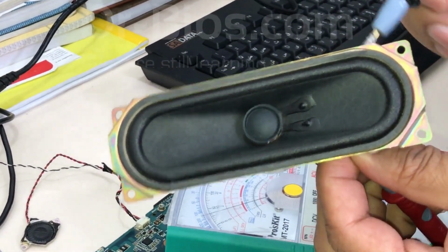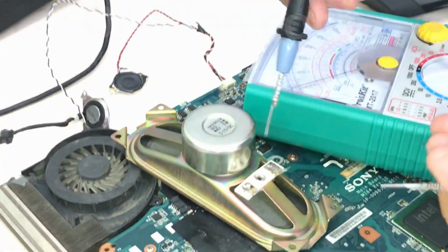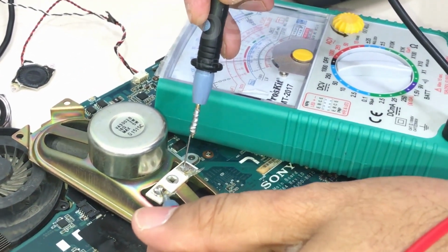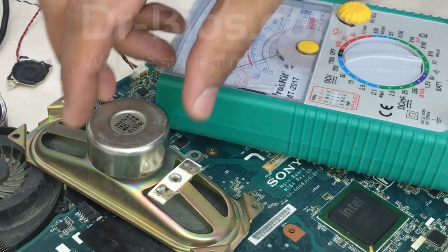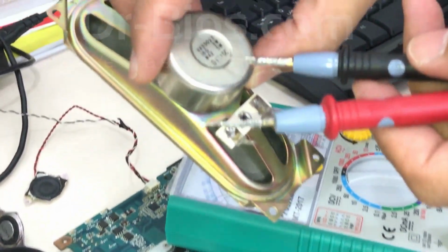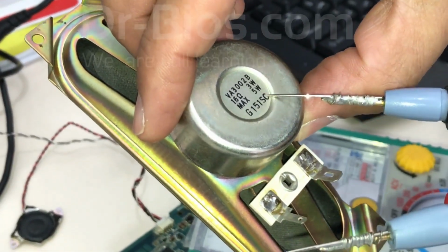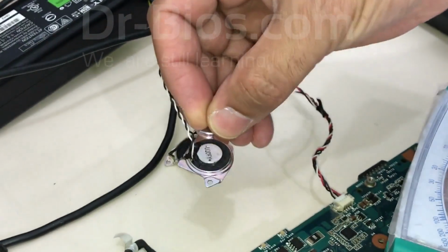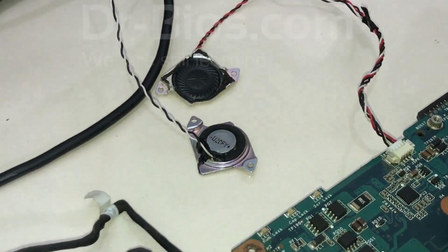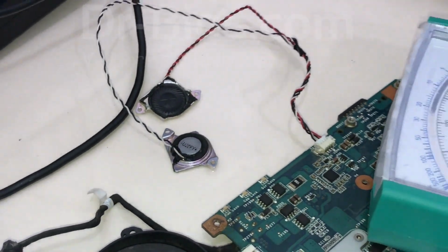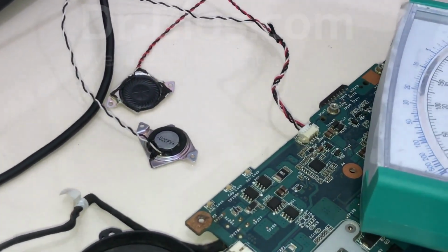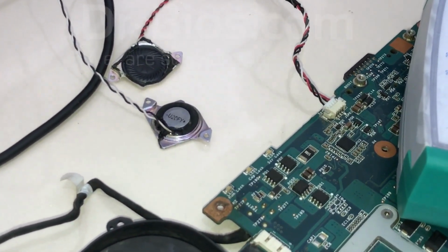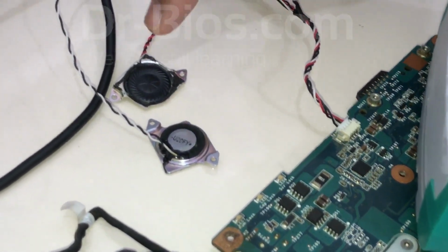How do you do that? I place and hold a probe on one pin and connect and disconnect the other probe on another pin. So it is like this. Speakers have resistance. For example, this one is 16 ohm and 3 watt, maximum 5 watt. This speaker is 4 ohm and 1 watt. There is a pair of 4 ohm and 1 watt speakers in the laptop. I have a question. For example, if a speaker gets out of order, should we consider wattage and ohm amount? Yes, and you need to consider the size as well.